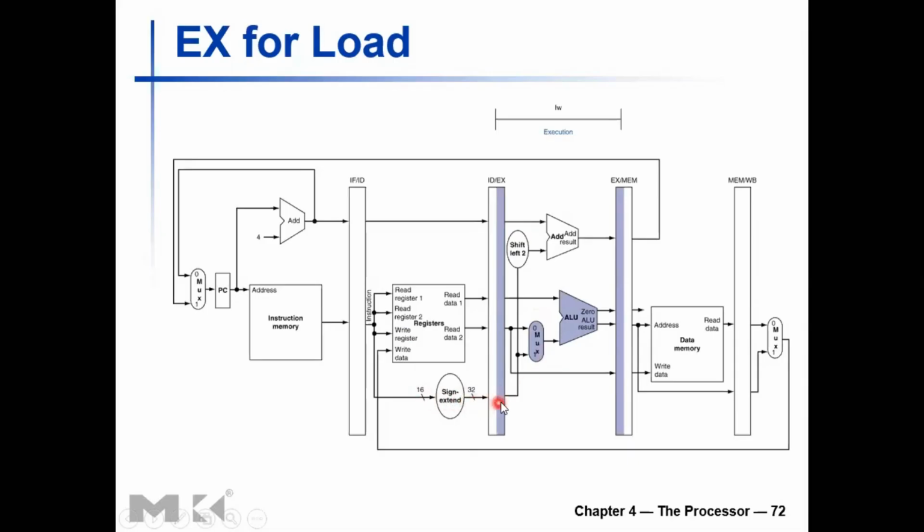So the immediate value written into the pipeline register will be connected to the 1 input, and the control signal should select that 1 input to be forwarded to the output here. So this line will update a little bit later than that line, right? So after the writing and reading delays of the pipeline register and the combinational delay of the multiplexer, you will have the correct value at this input to the ALU.